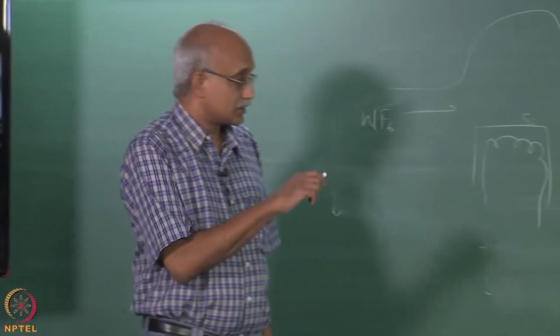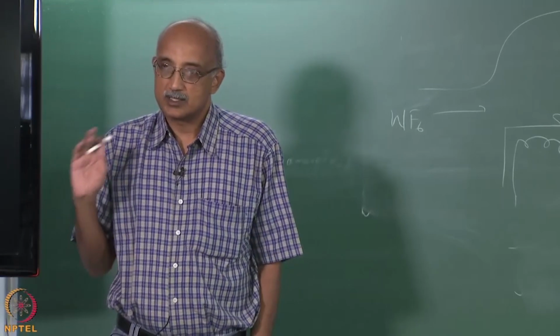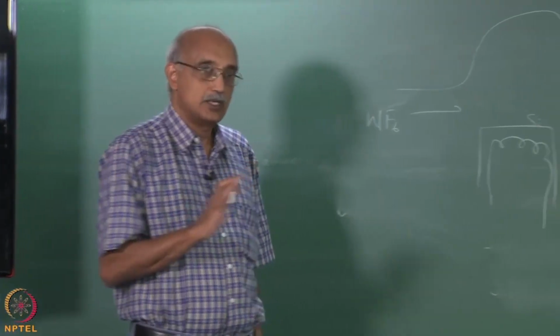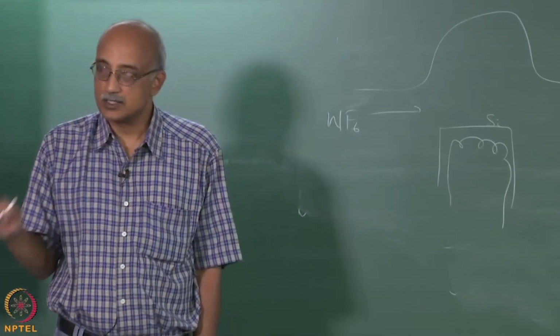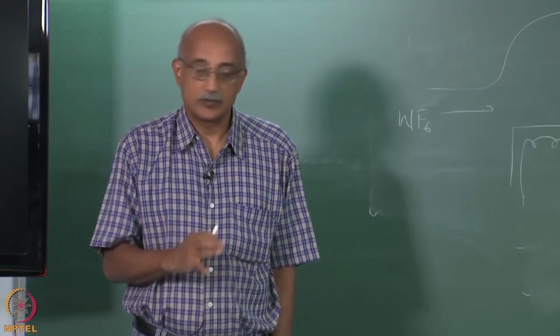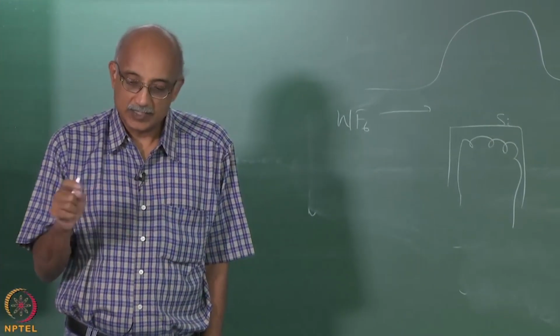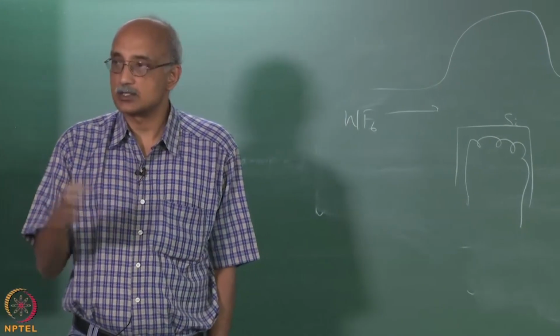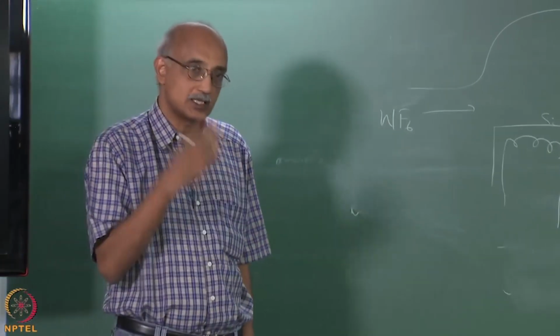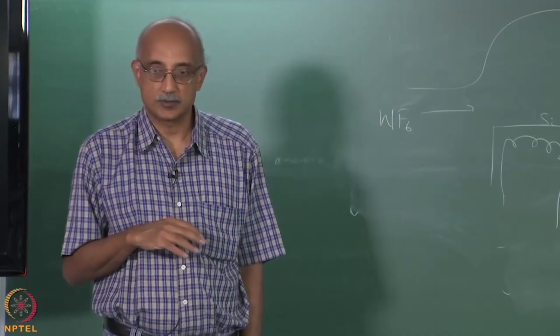Now, is this actually CVD or is it more like PVD? Well, strictly speaking it is CVD, because the film has a different composition than the reactant gases. However, in the gas phase itself you do not necessarily have chemical reactions taking place. The WF6 can stay as WF6 until it reaches the substrate and then react at the substrate.